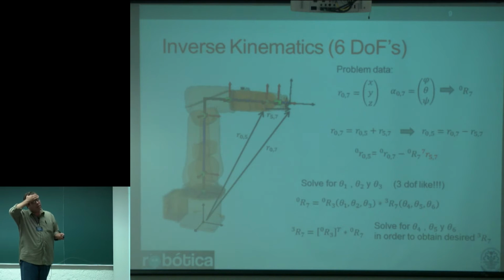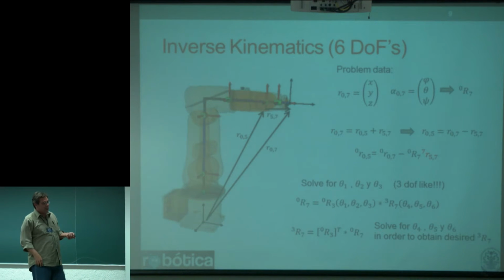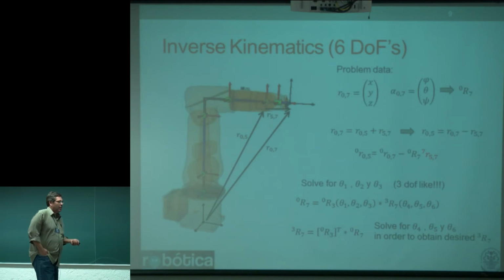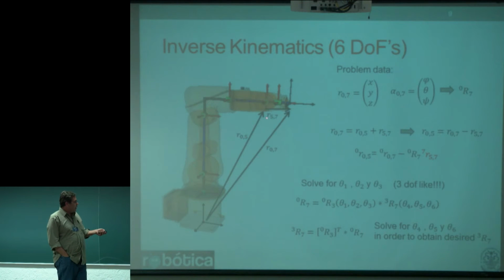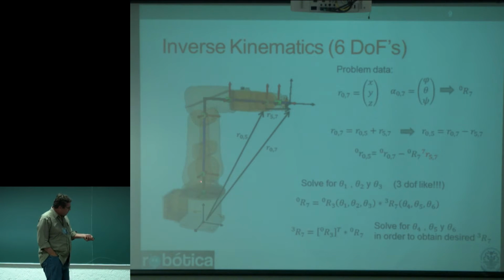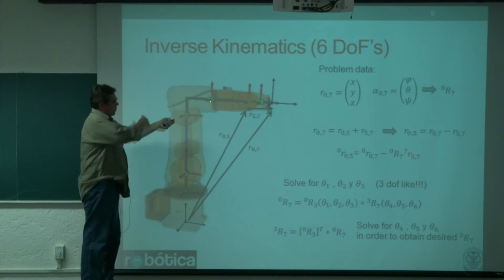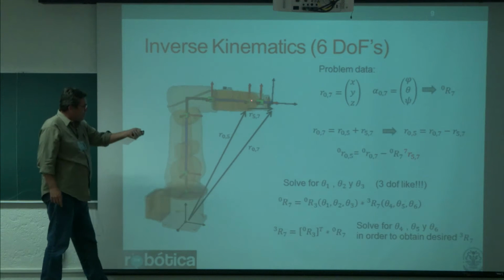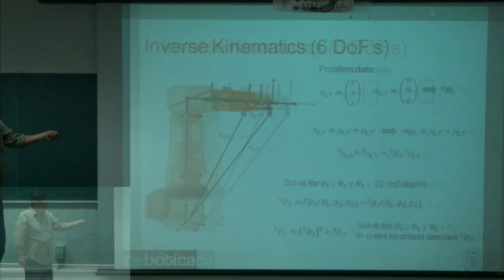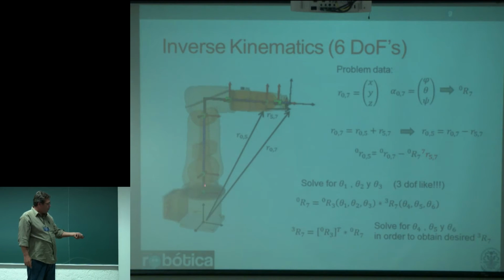This is kinematic decoupling, and it's based on Professor Spong's book. You can notice that we have 1, 2, and 3 degrees of freedom, and then this 4th will not affect the position of this point, because this will rotate in this. So we will fix there our end point for a 3 degrees of freedom problem.